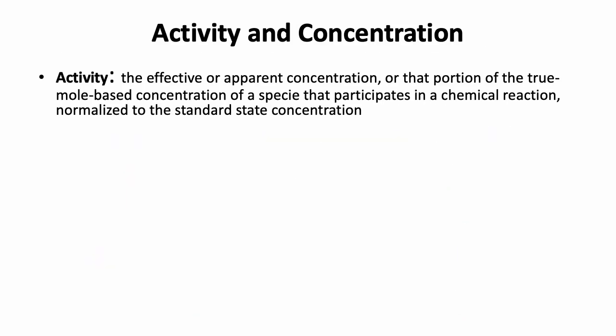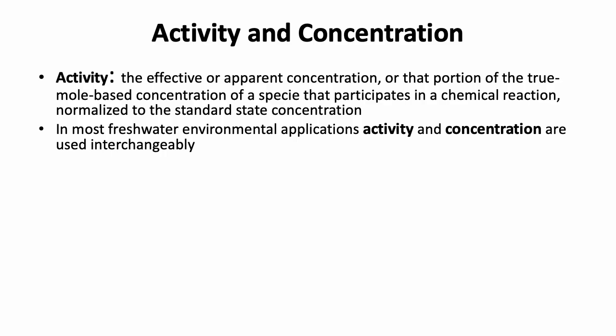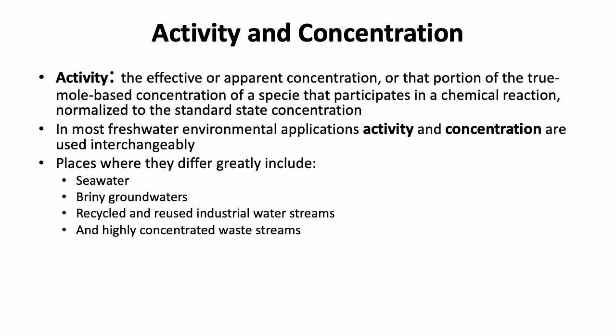So the activity is defined as the effective or apparent concentration of how compounds will react in a solution compared to a dilute or an ideal solution. In most freshwater environmental applications, the activity and concentration are used interchangeably. However, in seawater, briny groundwaters, areas where we have high concentrations of compounds, industrial wastewaters and other concentrated waste streams, and estuaries, we need to account for these effects because they'll change the chemistry and reactivity of the solution.